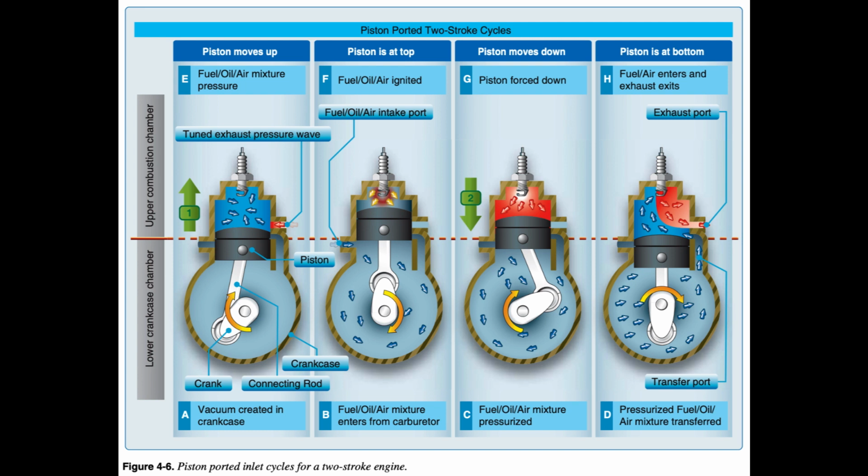Vehicles like motorcycles take advantage of this with the use of transmissions. Motorcycle exhaust pipe builders can optimize a certain RPM range and then the driver shifts gears to stay in that range. Aircraft, with no transmission, do not have this ability. On an aircraft, an exhaust pipe has to be designed to operate over a broad range of RPM from idle to full speed, a reason that simply putting a snowmobile engine on a WSC does not work well.